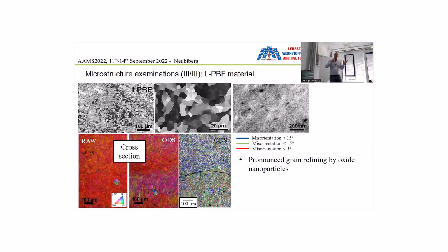It's the same methodology we used here for the LPBF. So we have a much finer grain than in the LDD. We see also this grayscaling, so the subgrain boundaries here. So it's kind of the same as what we also saw in the LDD part. And of course, you also see here, it's not that well visible, but you see those little black structures here, which are actually oxide particles.